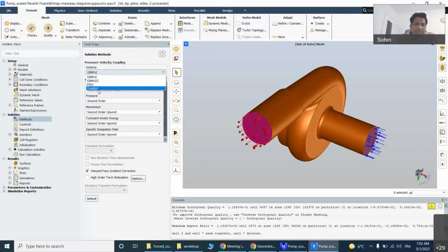That's why it's a bit expensive, but it's very good for some simulations, like natural convection where the density varies. We assume something, then solve the governing equation for the momentum, then again check the pressure by solving the pressure Poisson equation, which satisfies the mass continuity equation or the divergence-free field. But we can also use the coupled algorithm or the SIMPLE algorithm. Here we don't have much variation in density, so let's take the SIMPLE algorithm, no issue.